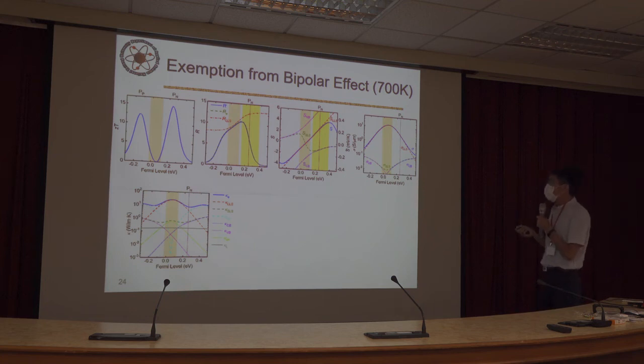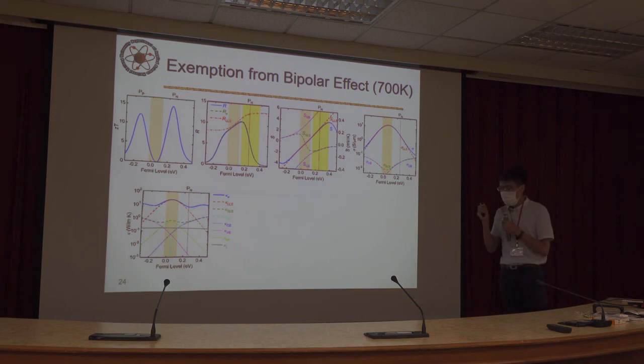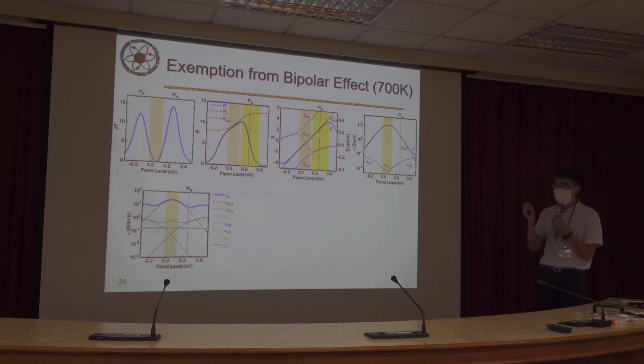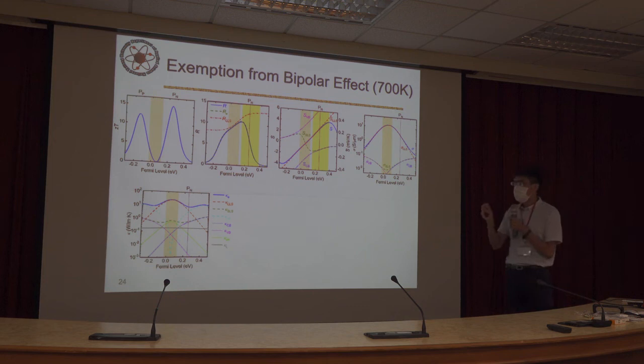And we notice that the bipolar effect on the semiconductors can be understood from our short-lived state result, because the short-lived state result shows the behavior of normal semiconductors. To examine the bipolar effect, we further decompose the short-lived state into the conduction band state, that is the state above the conduction band edge, and the valence band state, the state below the valence band edge.